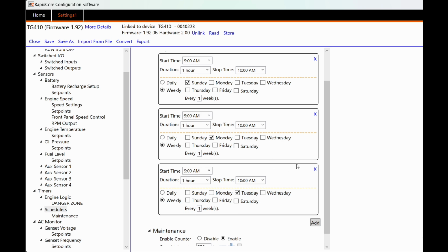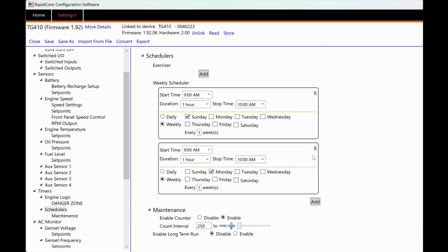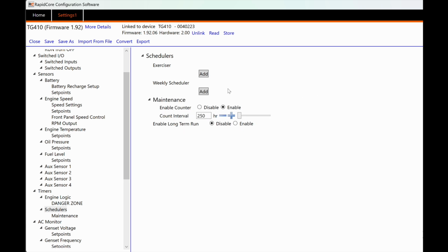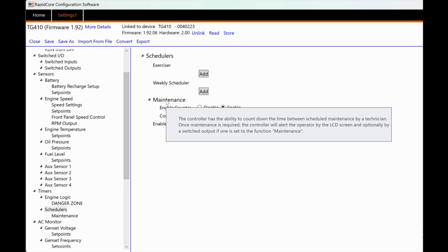We believe that running the engine for extended periods without sufficient workload can lead to the accumulation of deposits. It is recommended that you schedule exercises on a transfer switch instead, as it can also auto-start your generator and power your home to give it a proper exercise. When you have power and you switch to generator power, the transition is very quick and it seldom disrupts power to the home. This is far better than running an engine without a proper load.